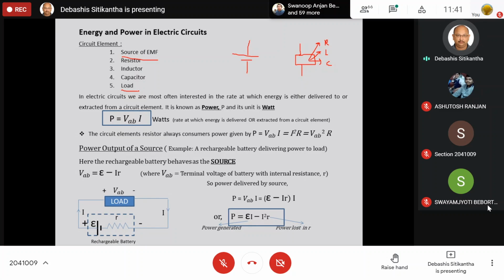That means when this pump is connected to the socket, it is going to consume around 735 watt of power. Similarly, your 1.5 ton non-inverter AC is something around 1500 or 1600 watt. That means it is going to consume 1600 watt instantly.